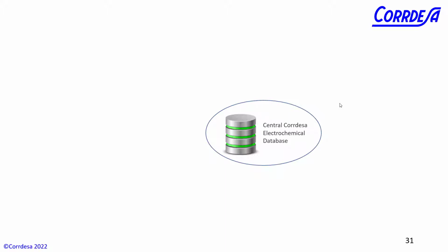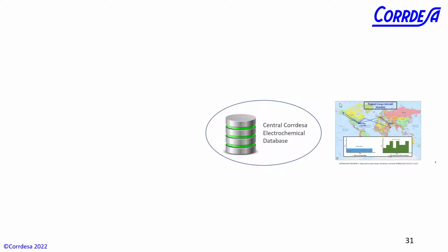We can learn a lot from that MIL standard, gather that automotive data, and then we could have an electrochemical database for automotive materials. Now then, I didn't go into this aspect on this Air Force program, but it's clearly relevant to the automotive sector as well. We have a methodology for taking these deterministic corrosion rate calculations and applying factors to them to take into account the actual life of an airplane, its mission profile.